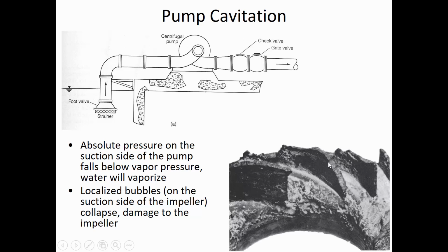What we'll see here is that change in pressure and the shock wave that it sends often occurs in pumps near impellers, because impellers are locations where the pressure of water changes very dramatically and quickly. Like this pump diagram is showing that what it's doing is sucking water from an origin, and here on the suction side of the pump, the pressure is low.